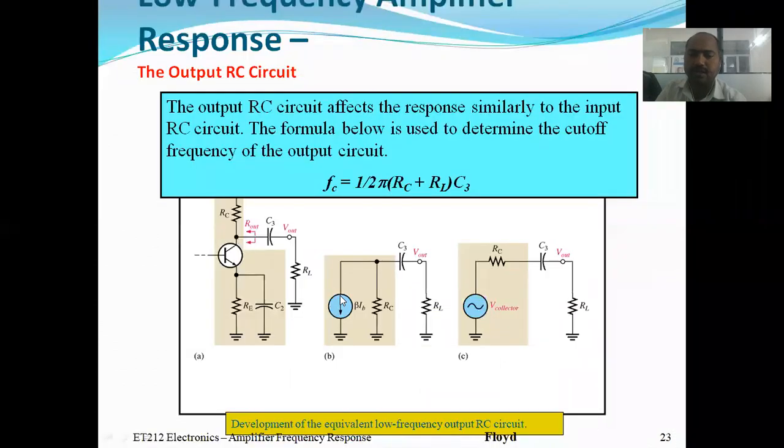We see only two capacitors, one is the coupling capacitor and the other is the bypass capacitor. This is the coupling capacitor, and it should be shown. Why? When we apply a signal with high frequency, these go out of the circuit. But when we apply a signal with low frequency, this output coupling capacitor, and before that the C1 coupling capacitor, are taken into this circuit, so they take part in the circuit. Why are they taken into the circuit?